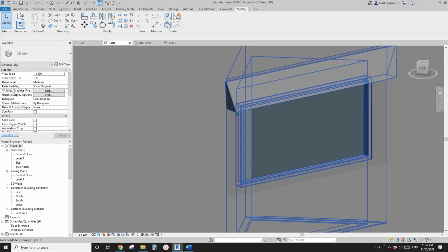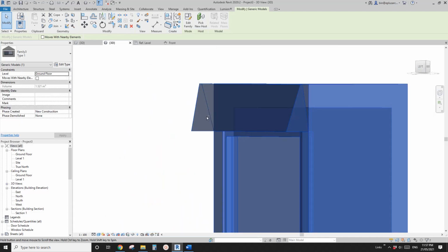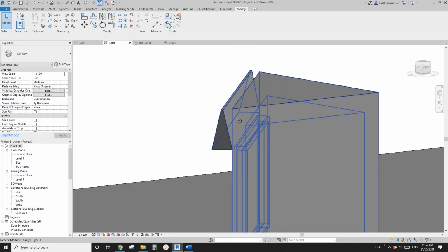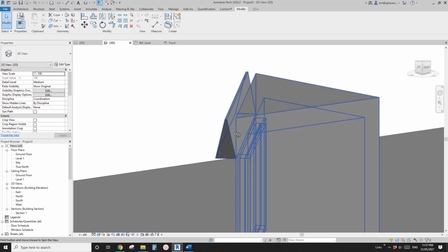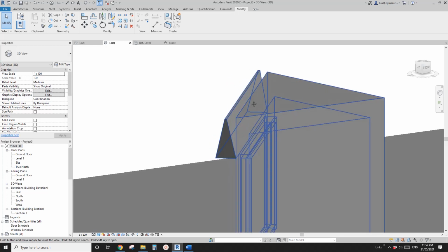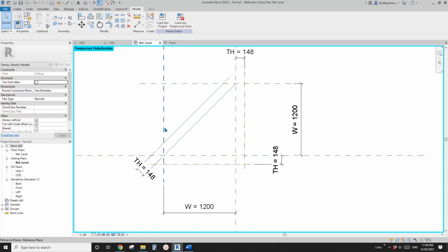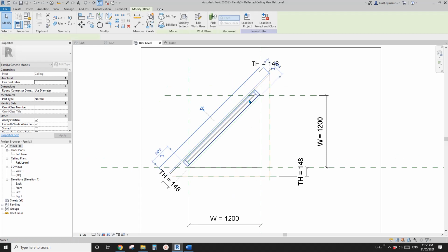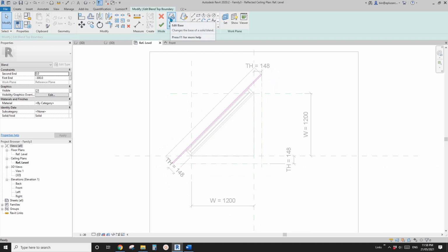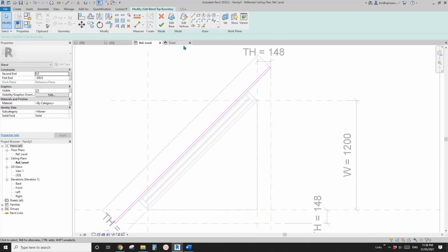Okay. Oh hang on, looks like something's not right here. Looks like when I created this profile of the blend, I think probably I didn't constrain it, so let's fix it. So go edit family. We need to select that. Okay, let's just type HR, so we show everything here, and select this blend. So let's edit top. Select this one. I'm not sure which one's the issue.